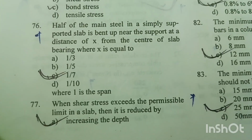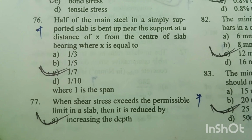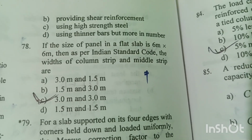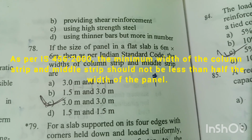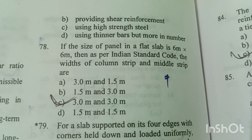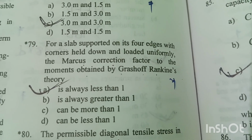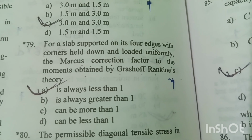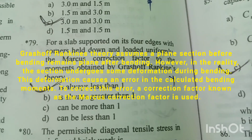Question number 77. When the shear stress exceeds the permissible limit in a slab, then it is reduced by increasing the depth. Option A is right answer. Question number 78. If the size of the panel in a flat slab is 6 meter into 6 meter, then as per Indian Standard Code, the width of the column strip and the middle strip are 3 meter and 3 meter. Option C is right answer. Question number 79. For a slab supported on its four edges with corners held down and loaded uniformly, the Marcus correction factor to the moments obtained by Grashof-Rankine's theory is always less than 1. Option A is right answer.